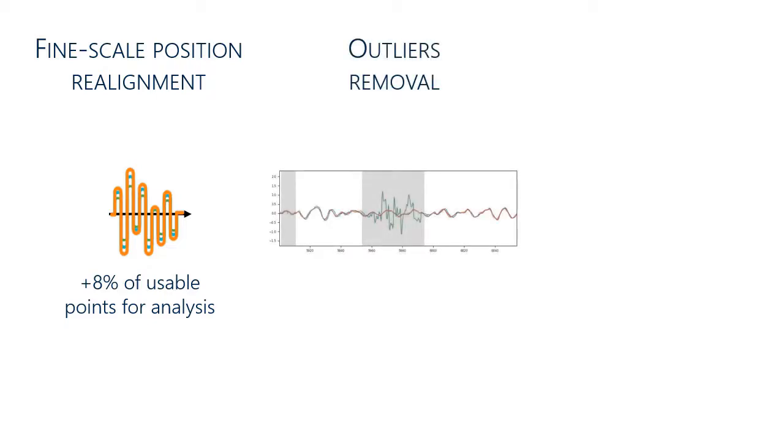Outliers can be caused by debris on the track or by instrument failures. They usually appear as high-frequency fluctuations in the signal. To be tagged as an outlier, the amplitude of the high-frequency signal does not need to be higher than that of normal measurements. We designed an adaptive filter that can locate outliers with an accuracy greater than 99%.